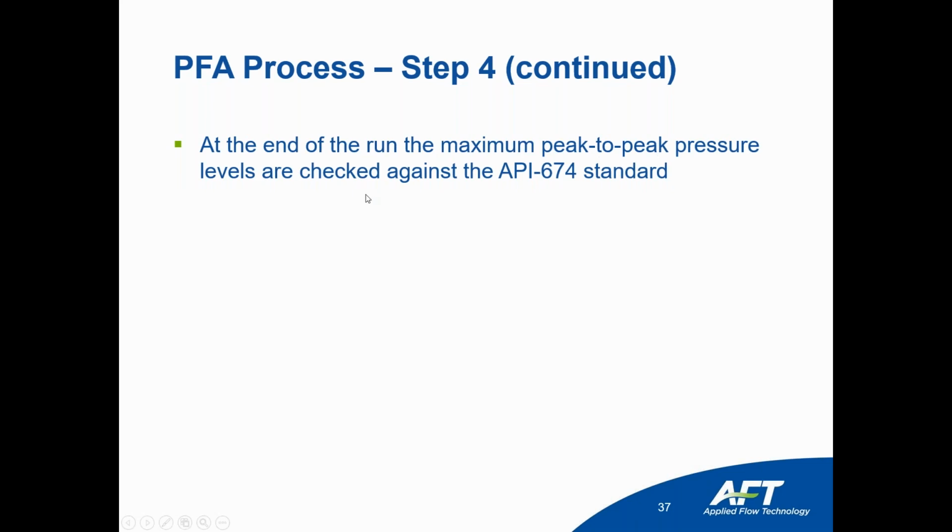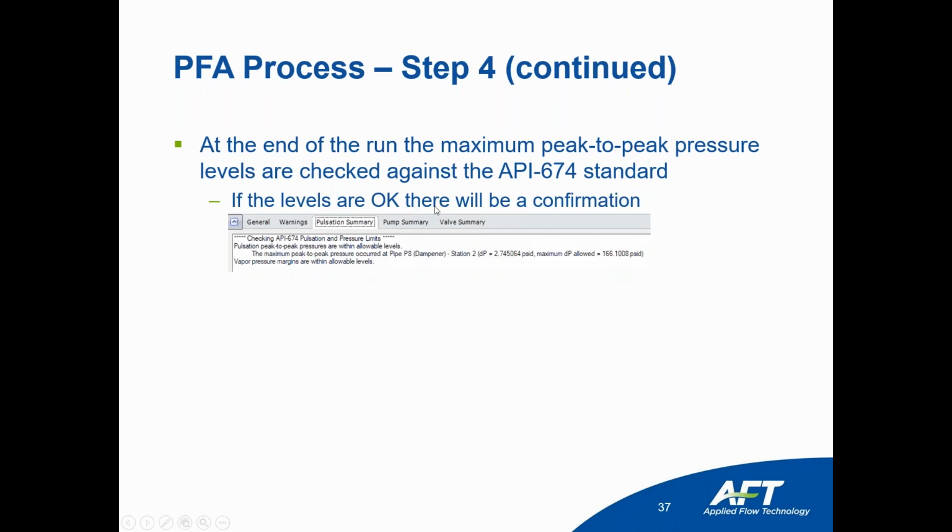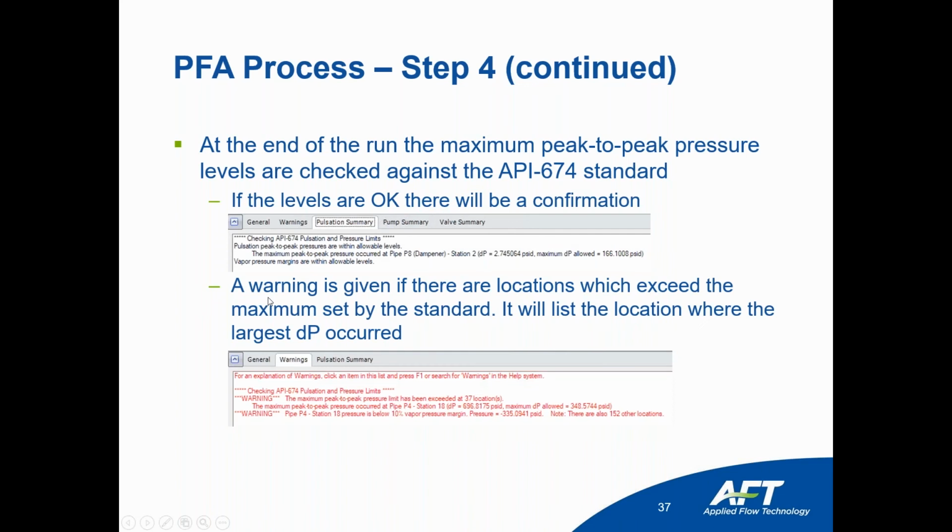And the reason for that is generally any change will change the acoustical frequency, the natural frequency of the system. So you have to check again whether or not it complies with the code. They are named with the pump speed frequency as we saw. The junction where the ring was placed is updated to be a flow versus time profile of the pump, and we saw this when we saw the transient. This is based on the number of pump heads that was specified when you defined the PD pump in the system.